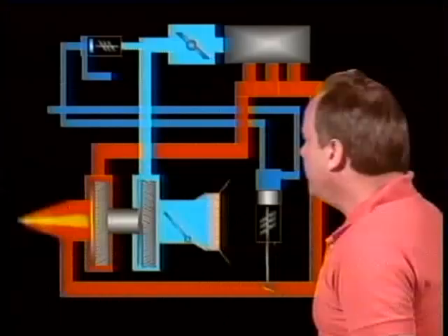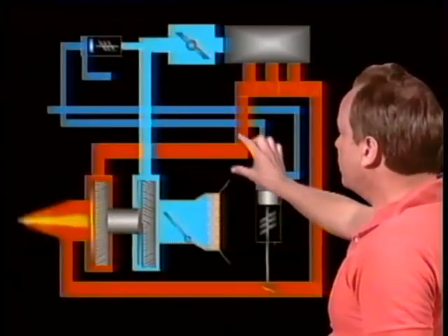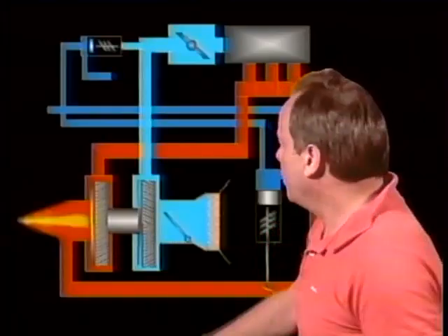First of all, the density controller says, we don't want to have any more than, and you name a figure designed into the engine, we'll say 34 inches of manifold pressure. And if the engine has 34 inches of manifold pressure or more, it will open the wastegate.